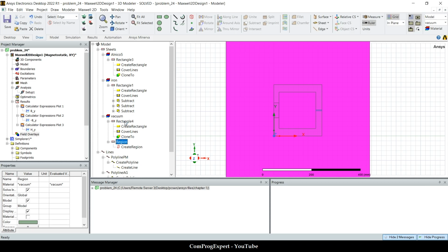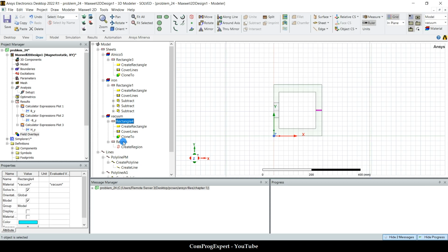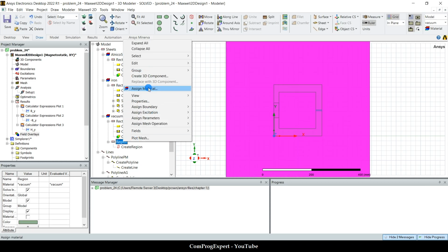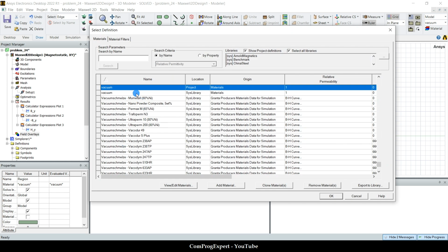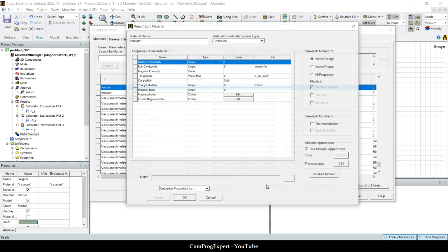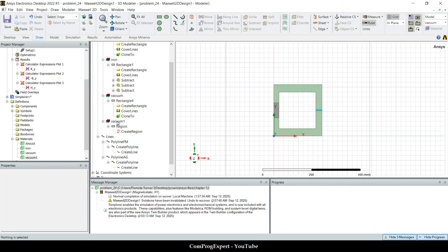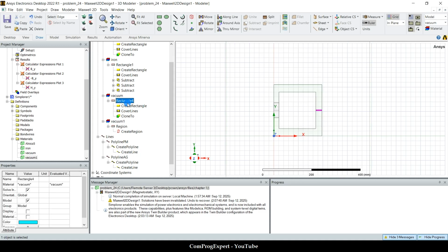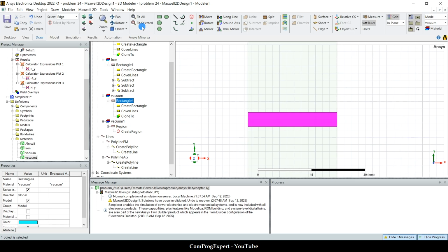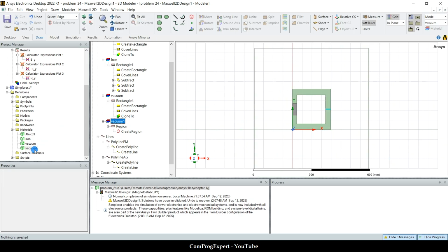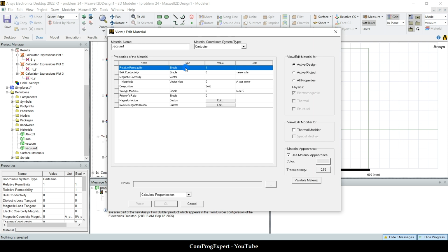So in this case, I need to set the material of the region again, the vacuum. I clone this material to define a new material. So this is the vacuum one, the fictitious material. Now we have this material, and this is the material for the air gap that we have like before. This is the air gap material. So for the vacuum one, the relative permeability is 1.